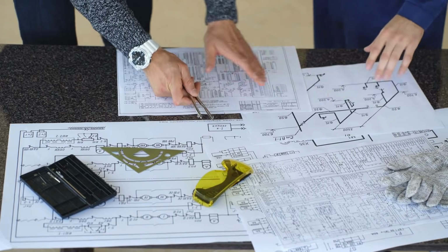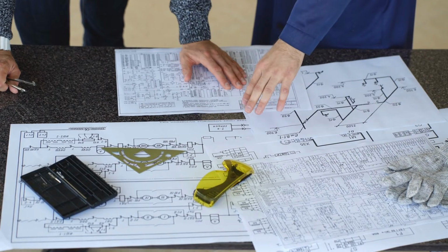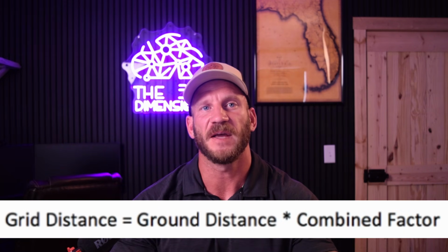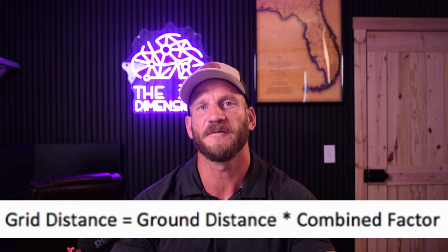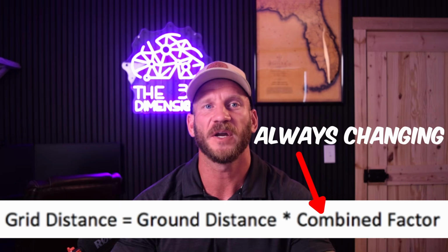If I'm laying out a building, the client will have plans of that building that are based off true ground distances, not grid distances. The builders aren't using grid tape measures. A grid distance of 100 feet in Denver is different than a grid distance of 100 feet in Florida. If grid distance is a product of a true ground distance scaled by a combined scale factor that's always changing depending on where you are, how can a 100-foot grid distance be a constant value?